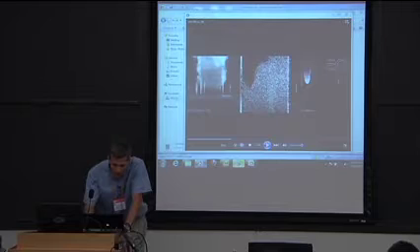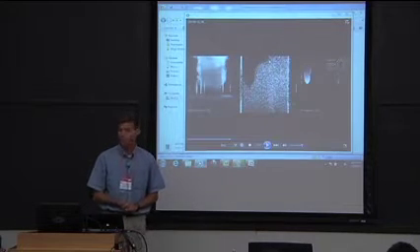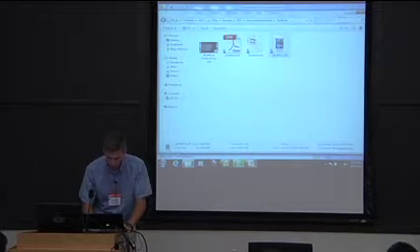And notice the shape of this flame. You can see it's penetrating farthest some distance from the combustor walls. This is the combustor wall. This would be an example of flashback in the boundary layer, and I'll talk a little bit more about this later.